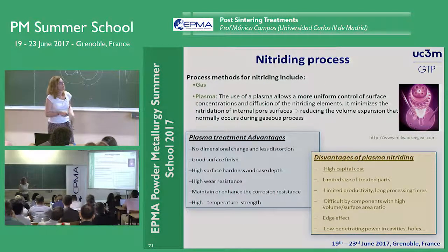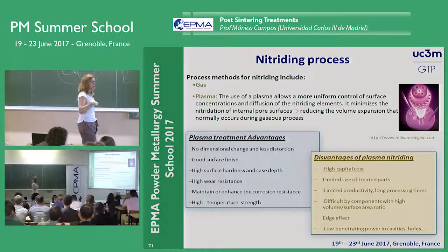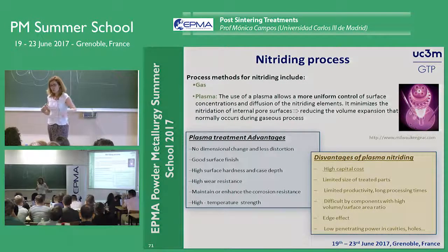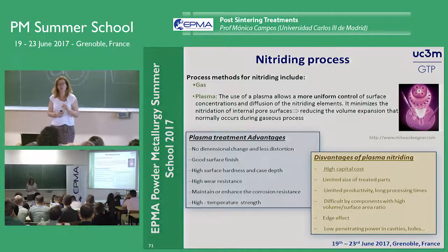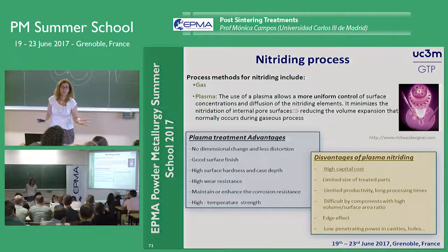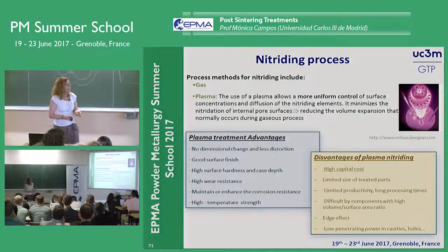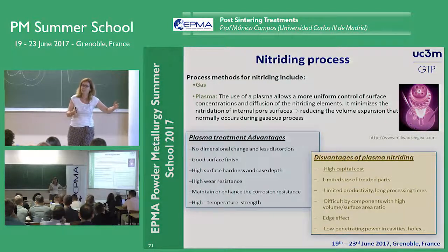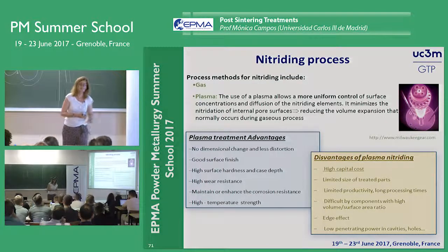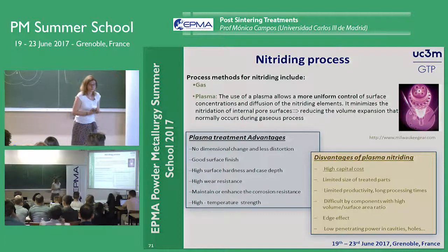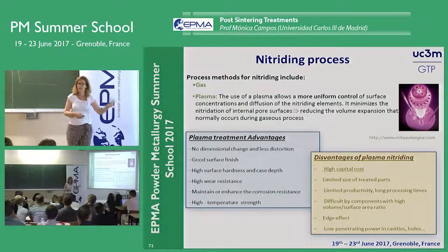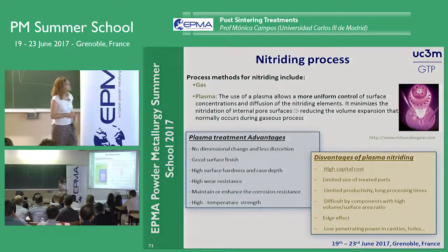There is another possibility, better than gas nitriding: plasma nitriding. Plasma nitriding works better, makes less distortion, and controls the depth of the treatment much more, but it's more expensive. Maybe the process is relatively longer to succeed with this treatment, which also increases the cost. But it's one of the best options because it offers the best results for nitriding processes.